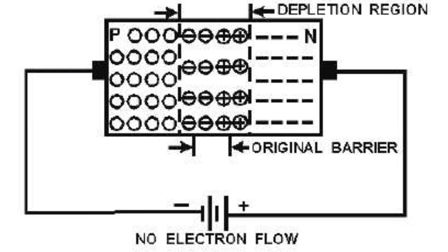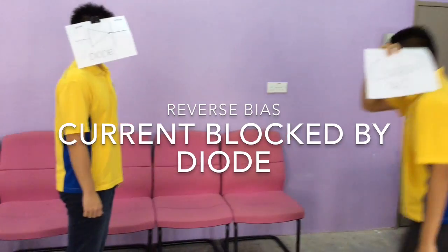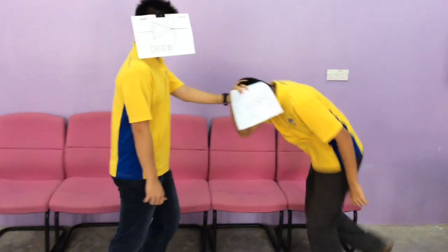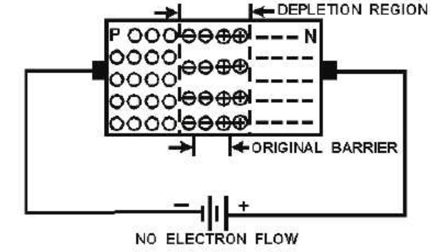Okay, now I would like to show the demo to you. AC current will change the direction of the flow of current. Diode is limiting the current flow in one way only. So we connect AC current and diode in a circuit. When it is negative half cycle, the current cannot flow through the diode. So that half-wave rectifier graph is shown. When there is strong enough voltage, it will break the diode.